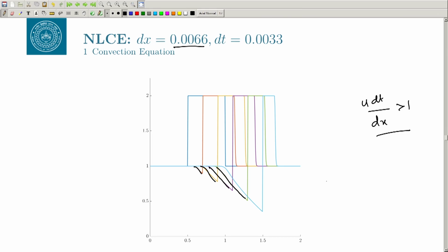So, what you need to do is every time you have to calculate the local delta t, the local Courant number, and your grid may be non-regular and non-uniform. So, your delta x may be different everywhere, your u may be different everywhere. Let us say here big, here small, here very small. But you have to make sure your lambda is less than 1. So, lambda is equal to u delta t by delta x, you know from your previous iteration the value of delta x. So, you calculate the delta t local at every cell.